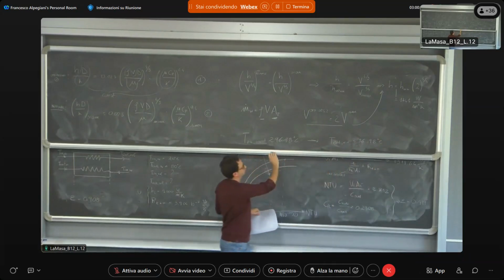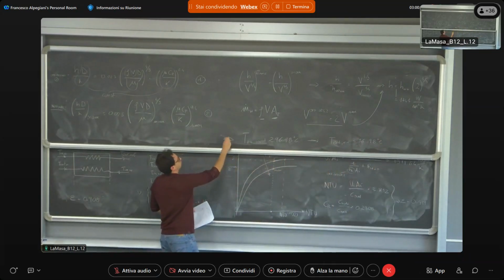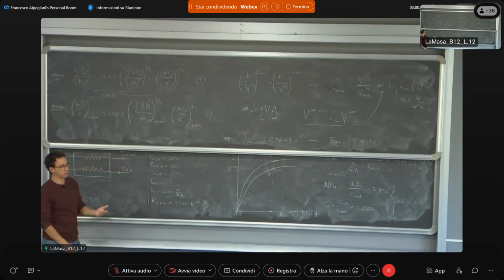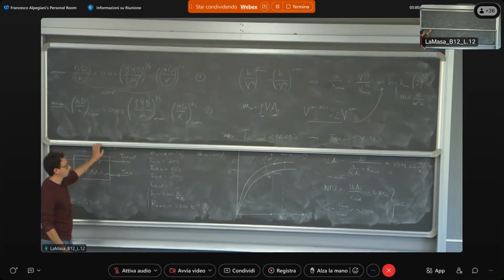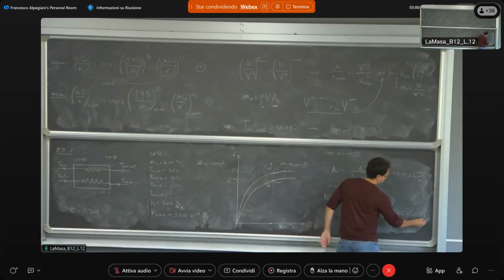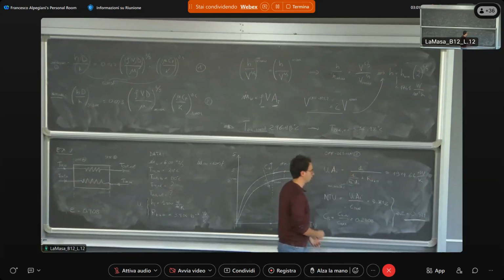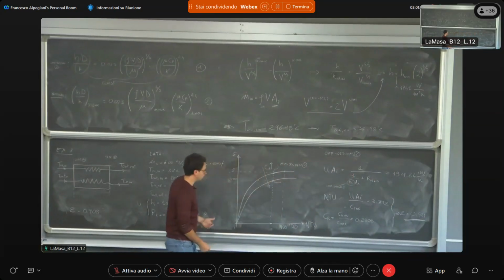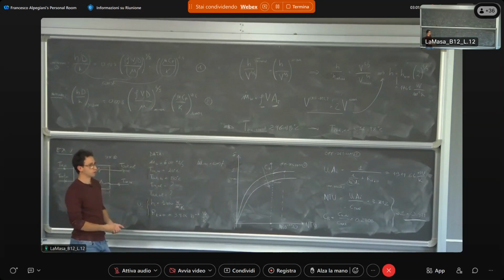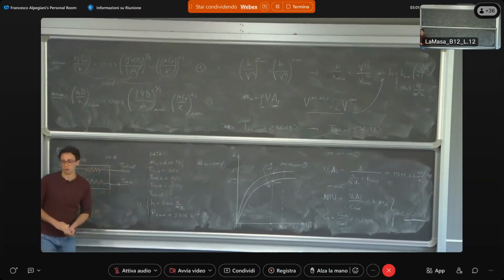So for this point, you have to use the same balance equation that we used before, but the important is more related to this. Okay, so once again, the effectiveness of the heat exchanger increases because the number of transfer units increases with the same CR. It's clear?